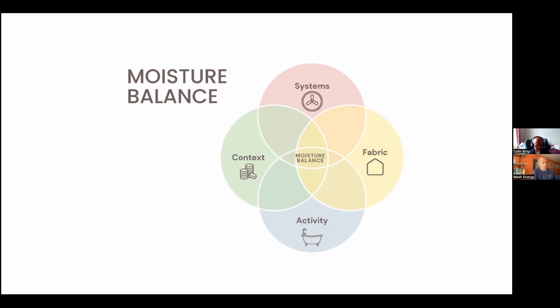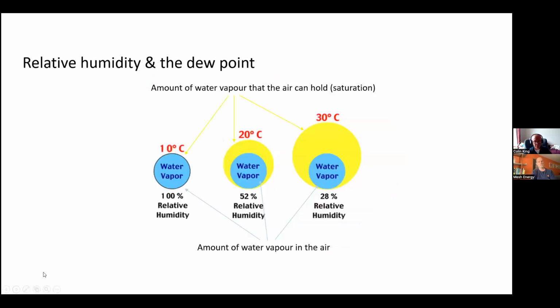And about 30% of the ventilation systems that were on the market when we did it didn't meet that requirement for quantities of ventilation. They're all updating it, but it does make a requirement that you assess the whole principle of the house, undercuts, background ventilation and whether mechanical ventilation is actually appropriate, which is more than it's ever been before.